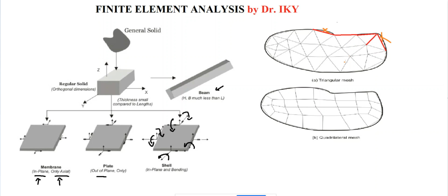Because of our mesh quality, these are gone. So you need to create a discretization of your system. If this is not so important, you can erase them. And generally, we are using something like this. And triangular. Instead of triangular, if the shape is so weird, of course, the computer will try to use triangular elements, but you need to push them. You need to force it to use quadrilateral or in 3D hexahedral elements.